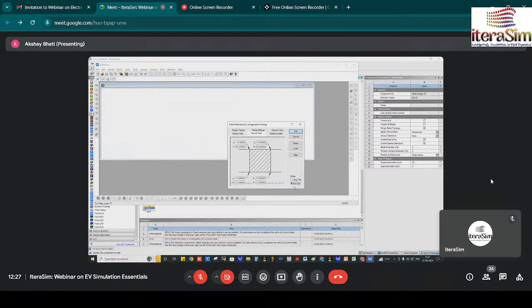So the radius will be 7.5 mm, but near the shaft we want to increase the thickness of the hub of the fan, so we consider a 12 mm hub radius on both sides, at the inlet and trailing edge, and at the leading edge.